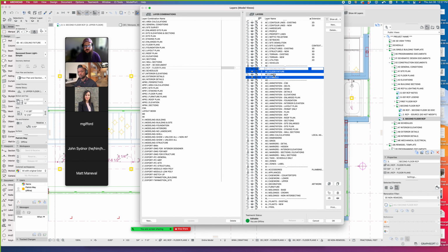The lamps layer is really not necessary anymore. The lamps layer was what we used for the short time that we were using CineRender to put actual light sources into ArchiCAD. I don't know that makes sense to keep in here because everything's really either ceiling, floor, or symbols. If it's a decorative table lamp or floor lamp, that's really part of the furniture package, so that doesn't even really belong in the electrical layers section.